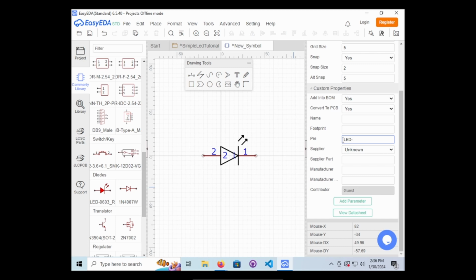And then usually, this is the prefix of the name, it'll have LED in it. We're gonna do DigiKey. So the question mark is where it increments, which actually we're gonna do diode. This is where it'll be resistor 1, resistor 2, resistor 3. It'll be diode 1, diode 2, diode 3. The name, we're gonna do LED.